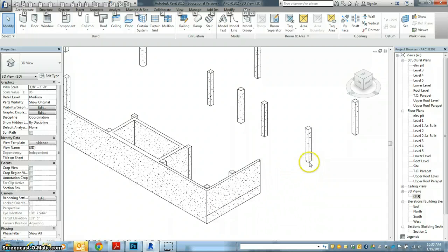The other thing you'll look on the plan, you'll notice that that low wall also goes between this column and this column, and then turns up and then becomes another, they've changed the interior wall type from a kind of a W12 to a W13, which is basically still an 8-inch block, but there is some structural modification. So if you want to make that wall type, you could change it coming up to here.